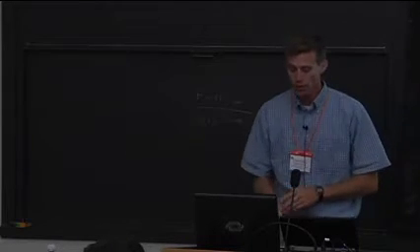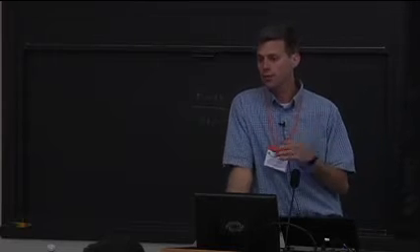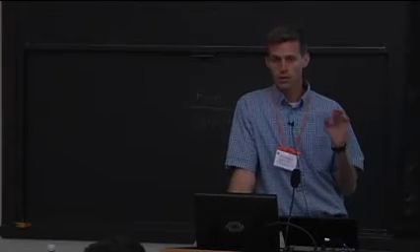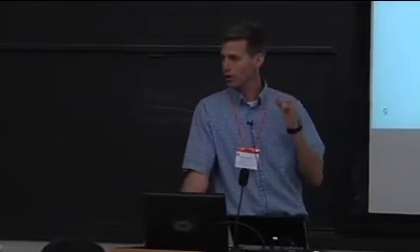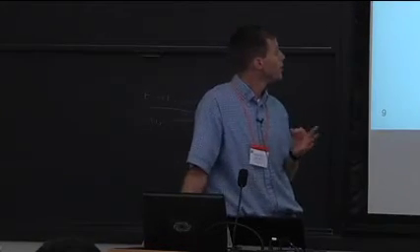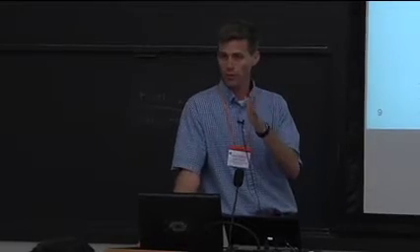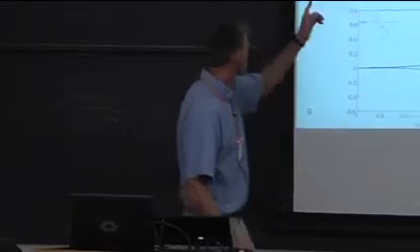And then actually, the first question I had asked you about your familiarity with the Darrieus-Landau instability: this actually causes stretch-insensitive flames to be intrinsically unstable. So you can't actually have a flat flame that just sits there. It's a nice mental construct for academics, but no real flame will just sit there without developing spontaneous wrinkles. And you can see that from this picture here.